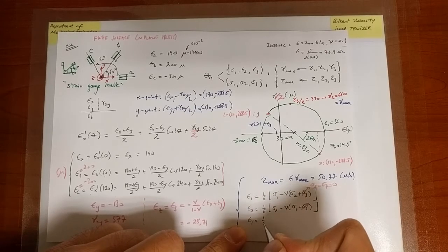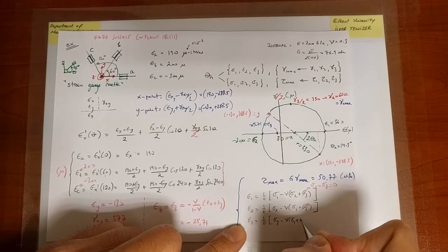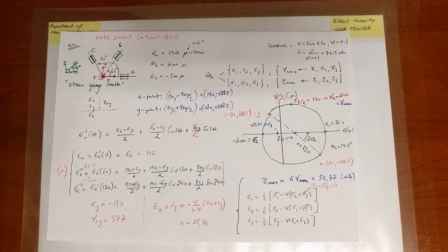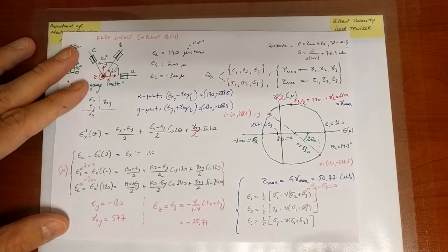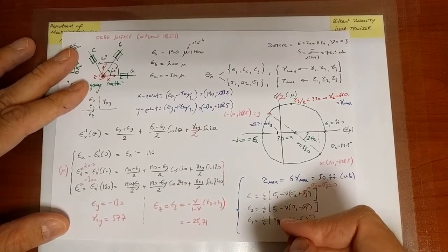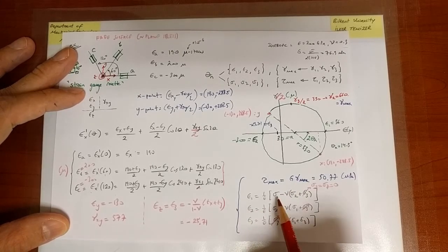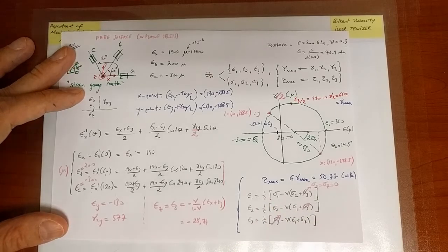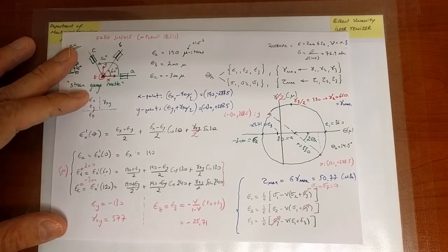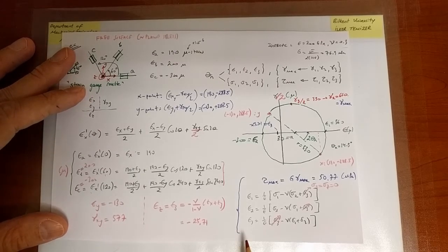Epsilon 3 equals 1 over E times sigma 3 minus nu times sigma 1 plus sigma 2. But that relation has already actually been implicitly employed here. So if you set sigma 3 equals 0 and plug in the expressions for sigma 1 and sigma 2 that you find from there into that expression, what you will eventually find is exactly a result that is equivalent to this one.